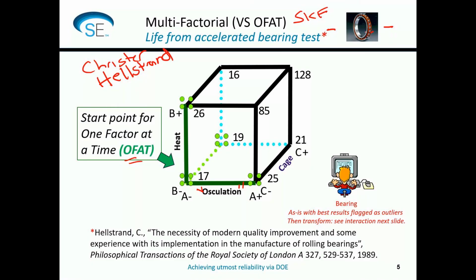So it relates to how tightly those bearings are fit in, and it's called the kiss of the cage. And so they thought for sure if they would increase the level from low to high, that would solve their problem, which was they were trying to get from 17 hours at the baseline, and they were trying to double that life, at the accelerated test conditions.